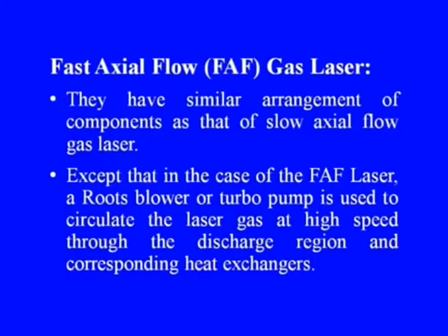In the case of fast axial flow, FAF, gas lasers, they have a similar arrangement of components as that of the slow axial flow gas laser, except that a roots blower or turbo pump is used to circulate the gas at high speed through the discharge region and corresponding heat exchangers.